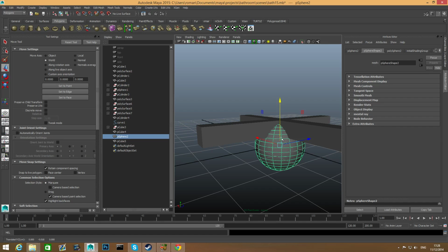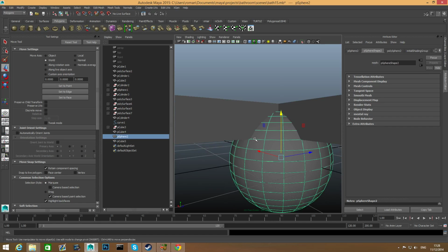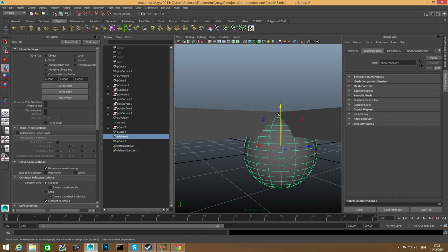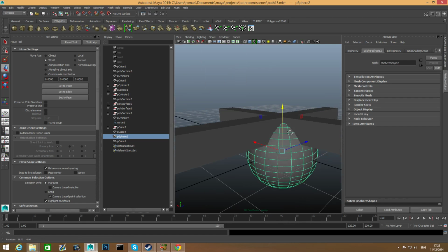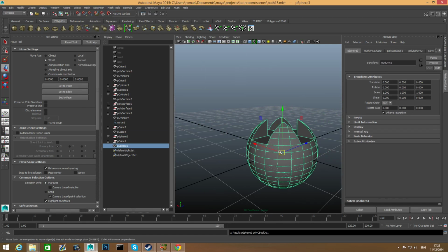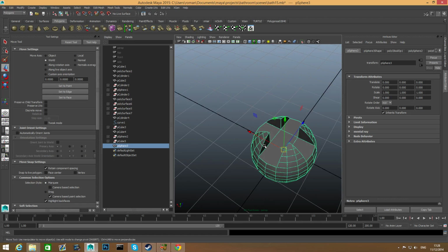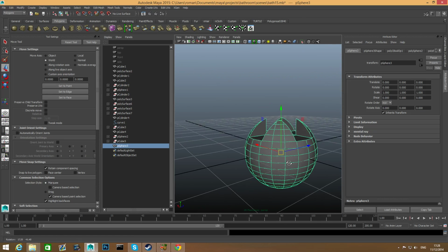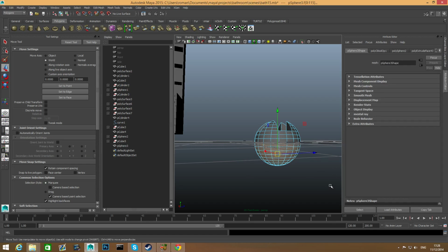So right now I'll just make sure that this thing here is sitting on top of one of those edges. Okay, see, still crossing it all over that way, and then shift select this and this, mesh, booleans, difference, and you can see now that I already have this screw surface there. So it's sparing me this whole thing, and I don't need to patch that all.